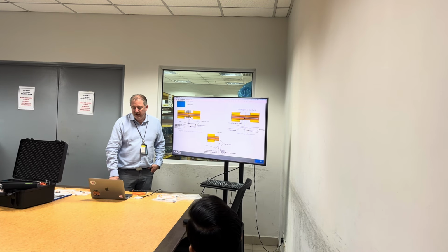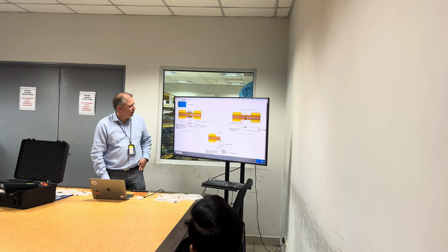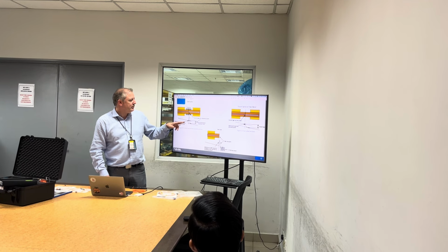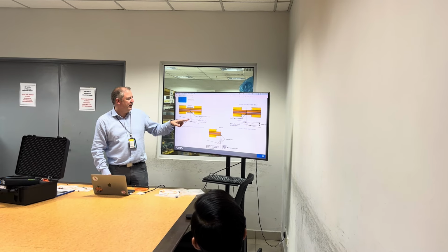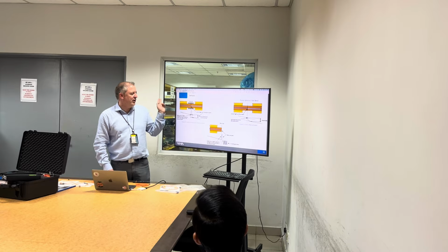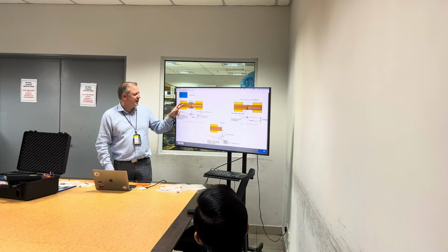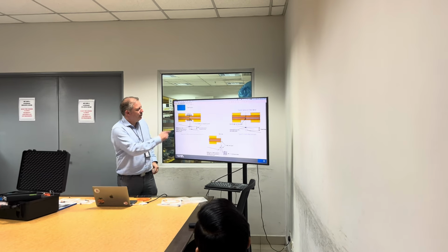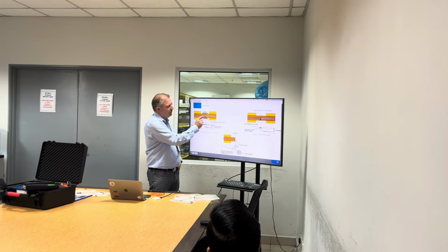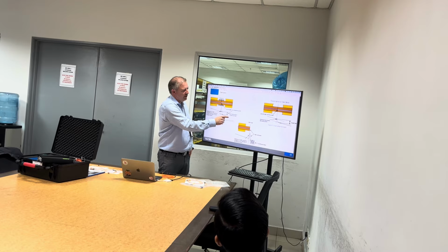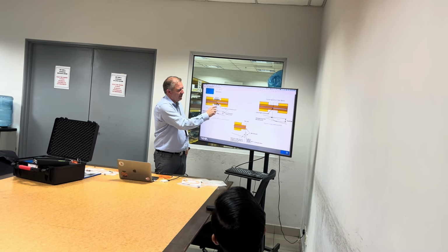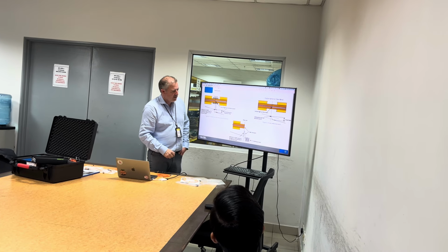So these are examples of faults. Improper connector, so that will lead to reflectance. Some light will bounce back. Some light will go there, and you see you have a lot of light here and very little here, and this is the typical graph that you will have, again with reflectance here, insertion loss here.